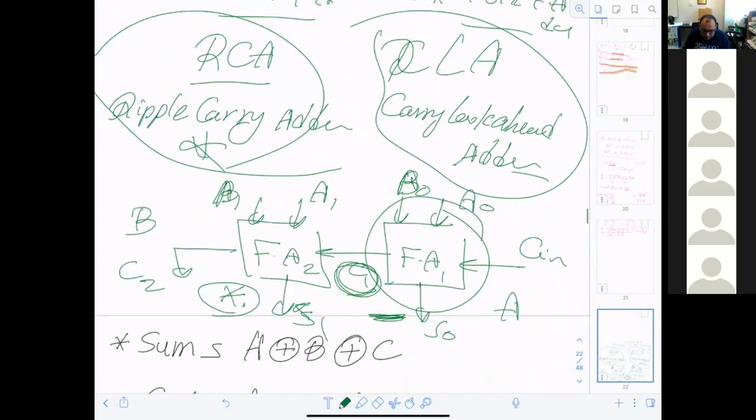To do this circuit using hardware description language is not that hard. Why? We're going to use instantiation. We have one full adder, I don't need to build it twice, right? So I'm going to take this one and repeat it twice in another file, and I will call it 2-bit full adder. Let's go back to the simulation environment and see how we're going to do this. Sounds good? Now, simulation.